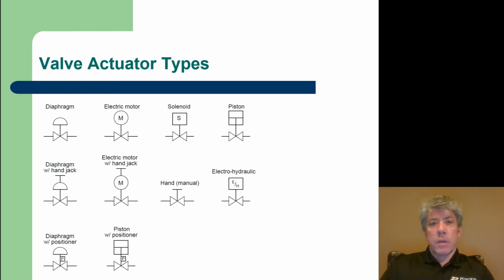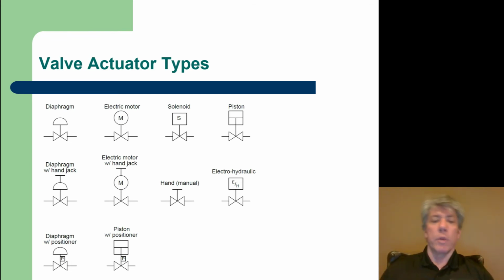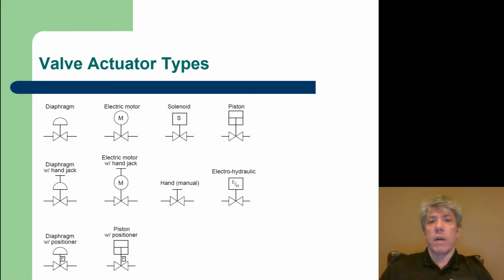Many years ago they introduced a proportional valve where instead of that rod being just either pushed all the way in or pulled all the way out, open or closed, what it did was you could actually turn the current on and off to the winding very quickly and float the spool within the valve, and so you had a valve that could be partially open or partially closed, which is a great advance over just a diaphragm valve. Diaphragm valves have their own sets of problems, and if you can just use electricity instead of any air, it can simplify the process for some applications.